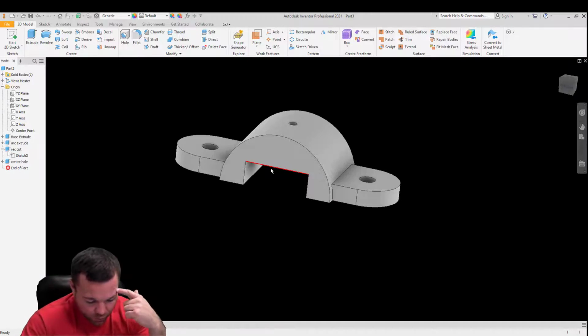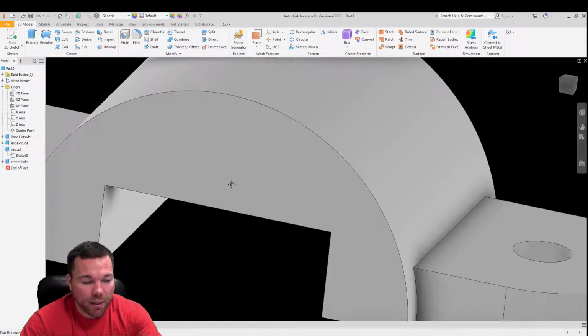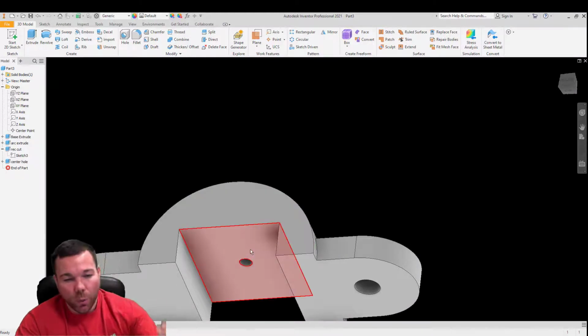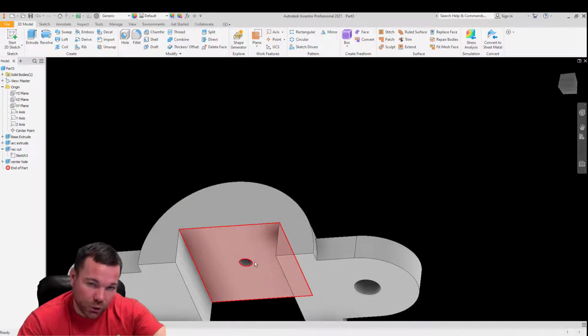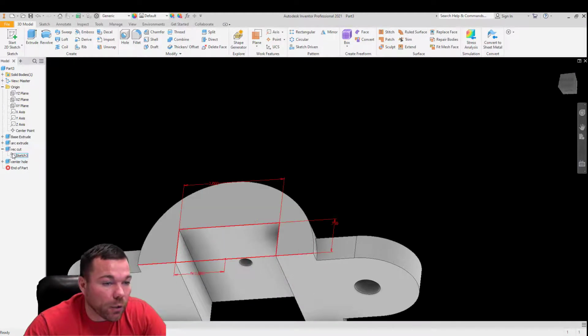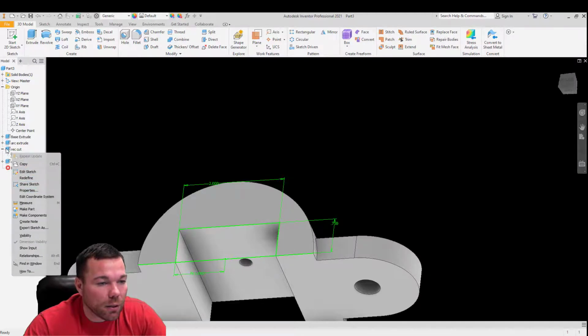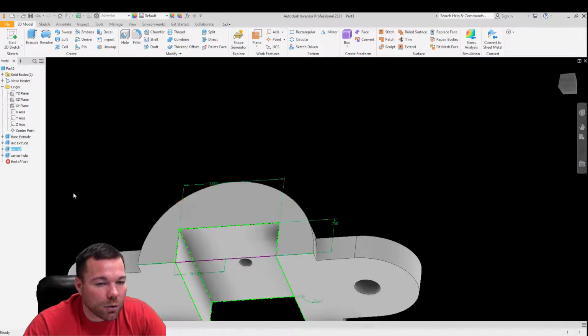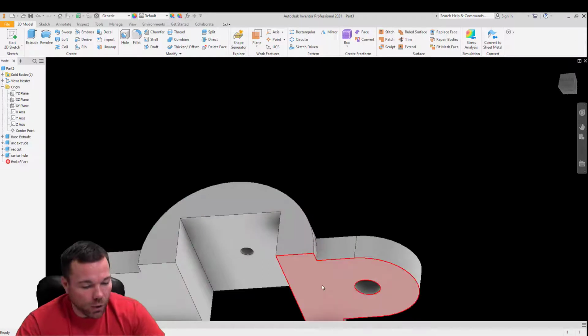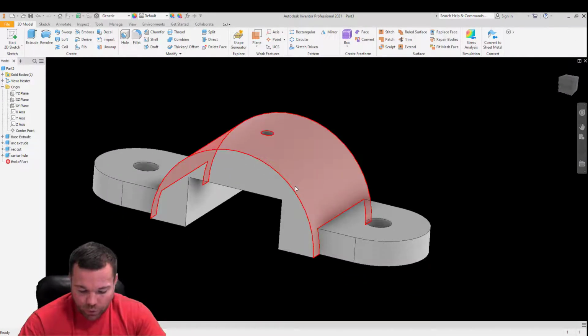Note that the position of the center drill feature is also adjusted as the placement plane is lowered. So in other words, rather than it just being solid right here, because our plane that we used was up here, we changed that plane, so it adjusts that automatically. When you adjust the height of the rectangle feature back to 1 inch, so let's go back and change that back. Show dimensions, 1.0. And this isn't anything new. We've gone over this before in other tutorials, but it's always nice to review some of this stuff.